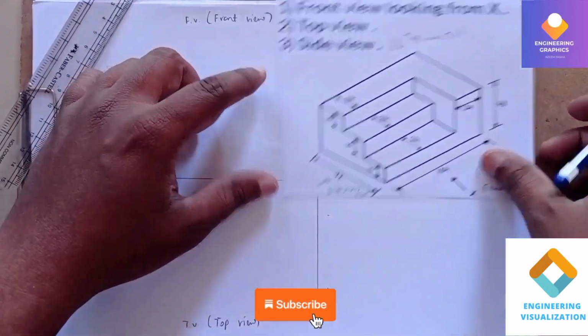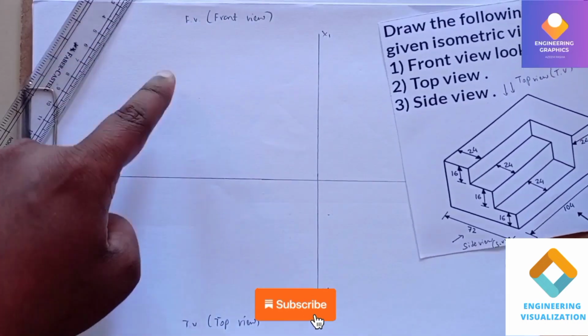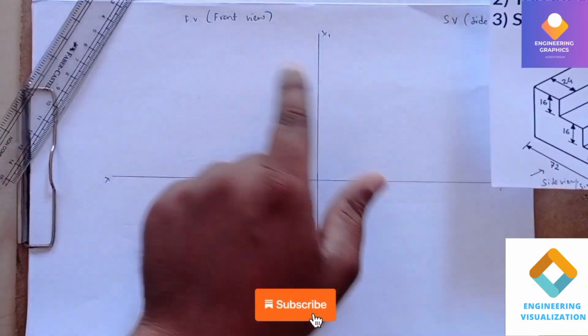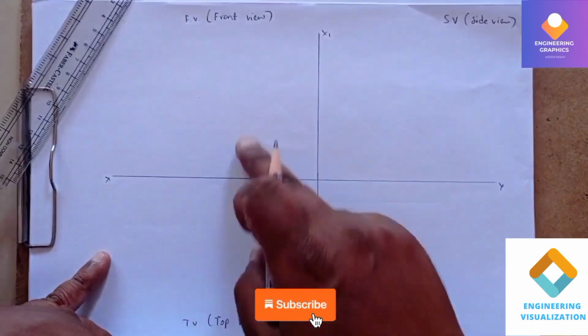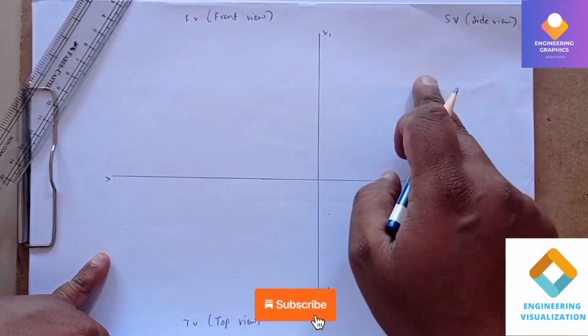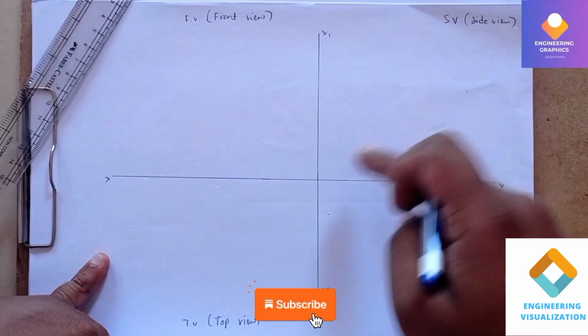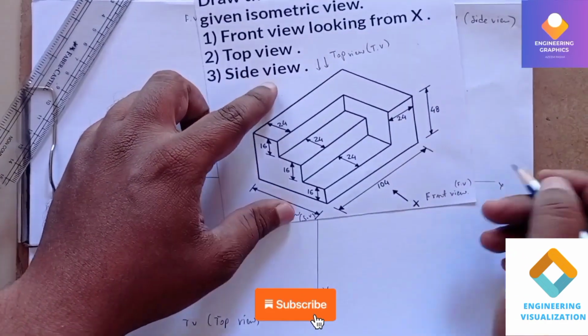You can analyze from the front view which faces are visible here. I'll be constructing the front view, top view and the side view. You can see the front view and side view are always adjacent to each other, and then the top view and front view will be in a vertical collinear line. Front view is always adjacent to the side view. In order to connect the top view with the side view, we draw a 45-degree angle line.